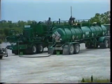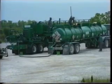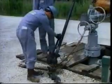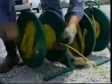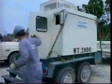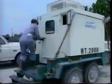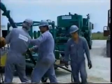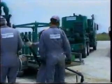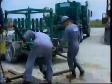Preparation for flowback or swabbing is made prior to pumping the acid. The shut-in time should be kept to a minimum after most treatments to reduce the risk of harmful precipitants. Usually 15 to 30 minutes of shut-in is required to allow for the safe rig down of the service equipment and rig up of the flowback equipment. In this case, it was decided that the well would produce directly into the production facility.